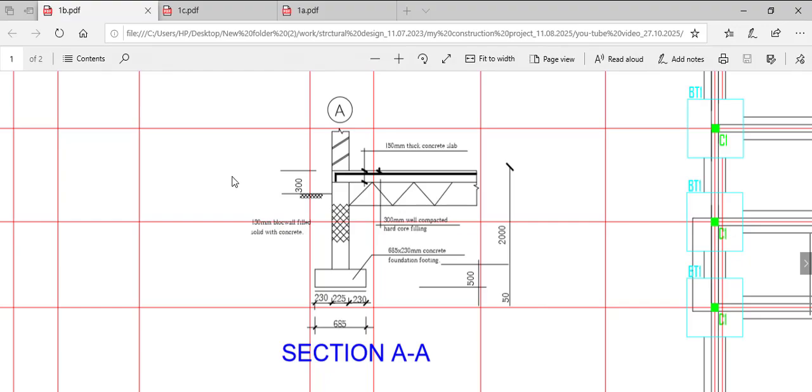If you don't do that, the runoff, the water from your road, will run into your plot, and your foundation will be lower than your road, which will cause areas of your plot to be constantly flooded, which is not a good thing. So that is very, very important.